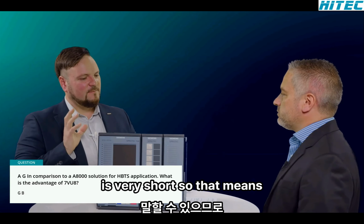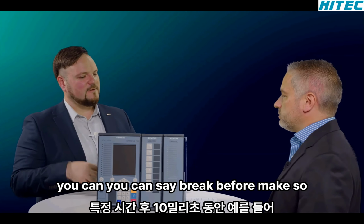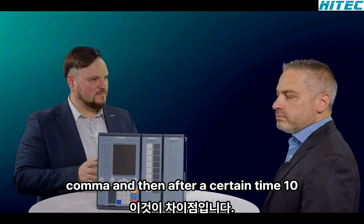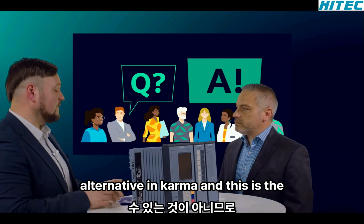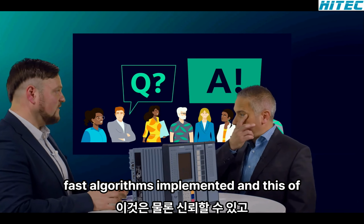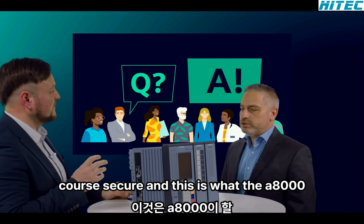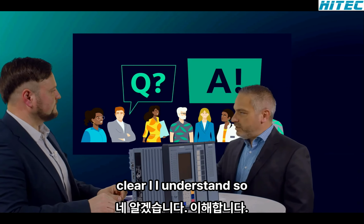So that means basically for the sequential transfer, you can say break before make. We open the first incomer, and then after a certain time, 10 milliseconds for example, we close the alternative incomer. And this is the difference. This is not what the A8000 can provide. Therefore, we have very fast algorithms implemented, and this, of course, needs to be reliable and secure. And this is what the A8000 cannot provide. Okay, that's clear. I understand.